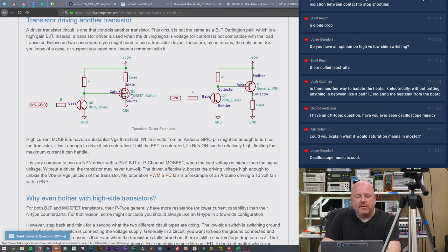Yeah, so if you're using an N channel with a driver, one downside is that this method inverts the logic. So a high here turns off the gate, and a low here turns it on. And then over on a P channel, I think it actually goes the opposite, because if I turn this off, this is off, that's at 0 volts. So, I'm sorry, if this is off, that's an open. So this is going to sit at 12 volts. Yeah, so if this is 0, this is off. So on a P channel driver, the logic is normal.